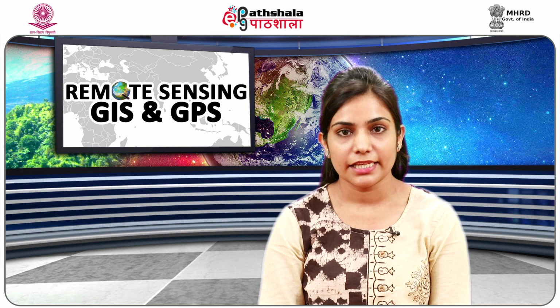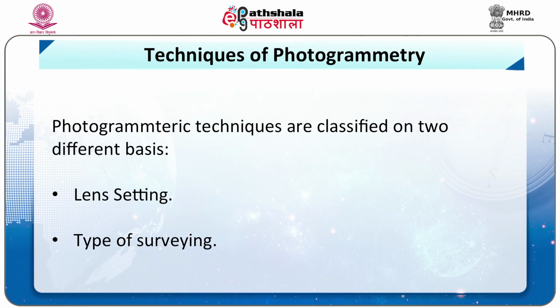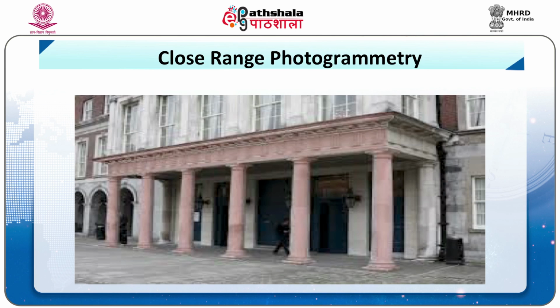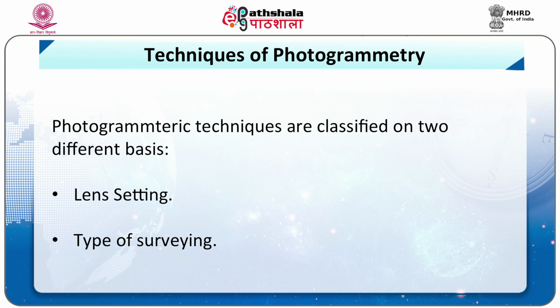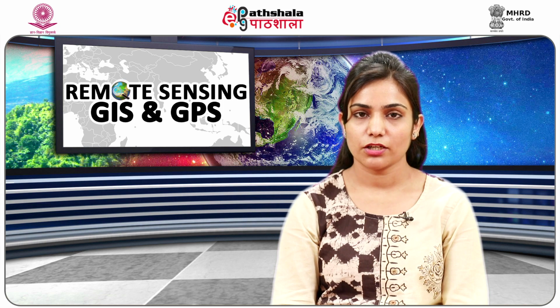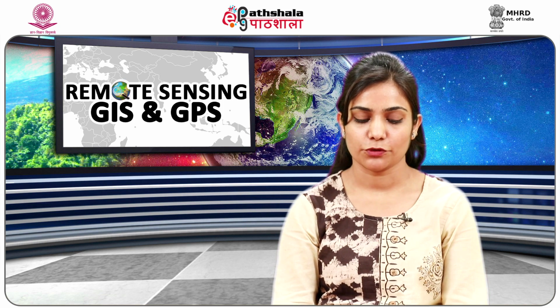Now coming to the techniques of photogrammetry. Techniques of photogrammetry can be classified on two different bases. First is depending on the lens setting. It is further classified as far range photogrammetry, which is with the camera distance setting to infinite. Next is close range photogrammetry with camera distance setting to finite values. Next is on the basis of type of surveying. This is further classified as terrestrial or ground photogrammetry and aerial photogrammetry.